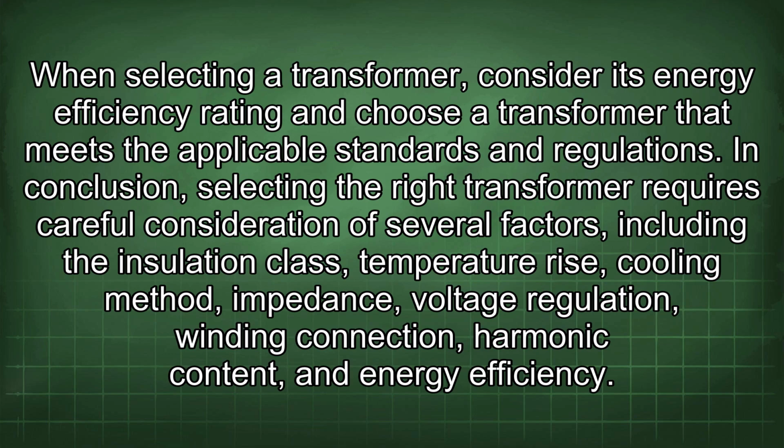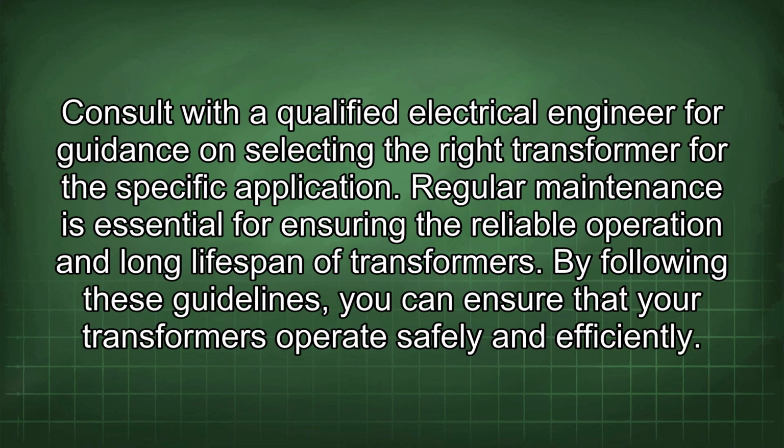In conclusion, selecting the right transformer requires careful consideration of several factors, including the insulation class, temperature rise, cooling method, impedance, voltage regulation, winding connection, harmonic content, and energy efficiency. Consult with a qualified electrical engineer for guidance on selecting the right transformer for the specific application. Regular maintenance is essential for ensuring the reliable operation and long lifespan of transformers. By following these guidelines, you can ensure that your transformers operate safely and efficiently.